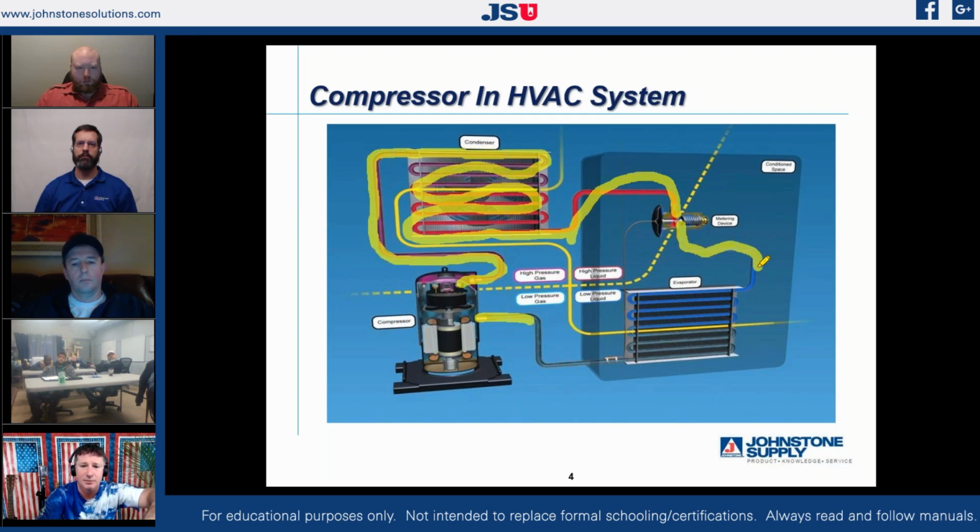So we're going to have a liquid that is starting to already be dispersed as it hits our evaporator, but it's still liquid form, still liquid droplets. As we get through that evaporator, we're going to blow our warm air that is warmer than our vapor temperature, and we're going to try to absorb some of the heat from our space, and we're going to assist that boiling process. Because remember, when I reduced that pressure at my metering device, it's going to boil on its own. I don't have to have the heat from my space across that. We're going to try to introduce some of our heat across that evaporator and absorb it and assist that boiling process. And as we pass through that evaporator, we're going to boil off all of our liquid refrigerant because that's where the work is happening. Our energy is being transferred in that expansion and contraction and that release of heat off from our refrigerant as we're boiling. That's where our work is happening.